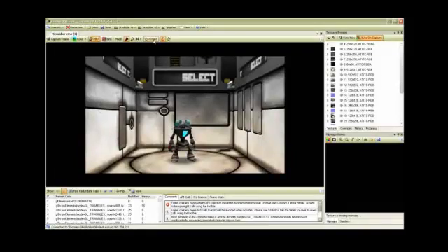So let's take a look at this. The first thing I want to draw your attention to is down here at the bottom in the comments panel. Since we've found that a lot of people run into the same kind of issues over and over in developing graphics applications, we look for some of the most common mistakes that people make in analyzing the call trace, and we identify those. The first thing you want to do when optimizing your application is look through this and see the suggestions we have for things that you might want to improve.